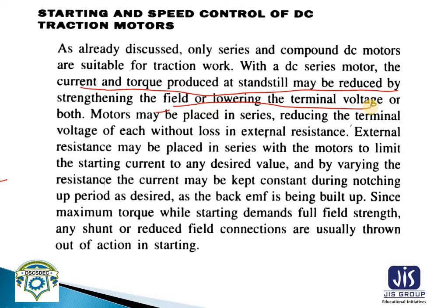Motors may be placed in series, reducing the terminal voltage of each without loss in external resistance. External resistance may be placed in series with the motors to limit the starting current to the desired value.